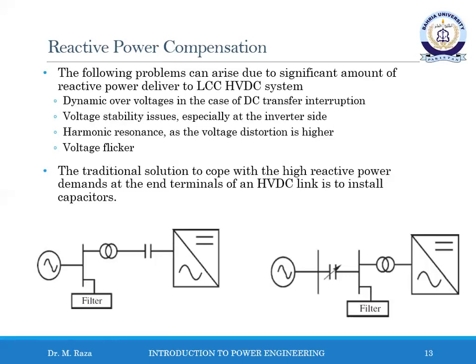Thyristor-based HVDC systems have different converter topologies as shown in the diagram. The capacitor commutated converter is a configuration used by certain manufacturers in which a series capacitor is inserted between the transformer and the converter, which is shown in the bottom left diagram. Other manufacturers use a different configuration with a similar result, such as shown in the bottom right diagram.